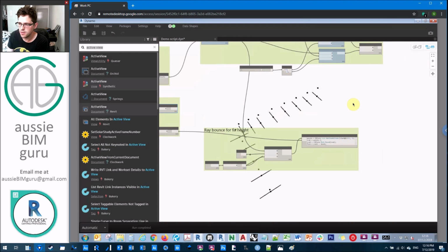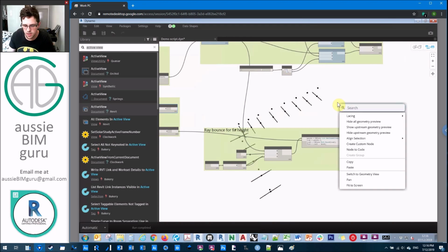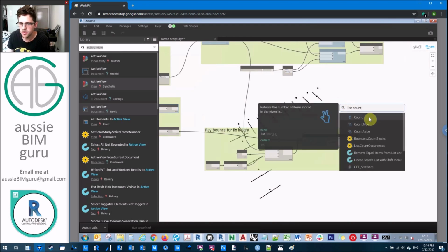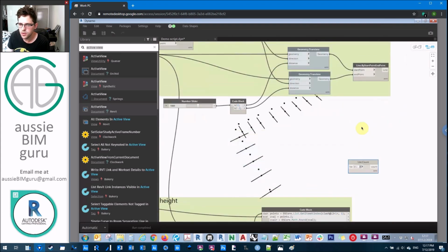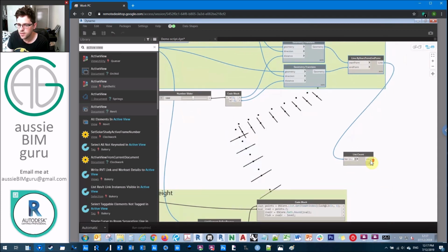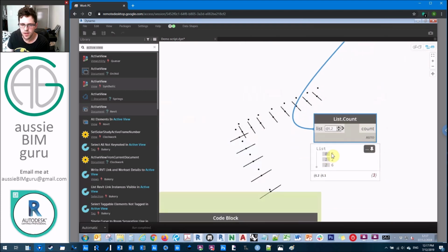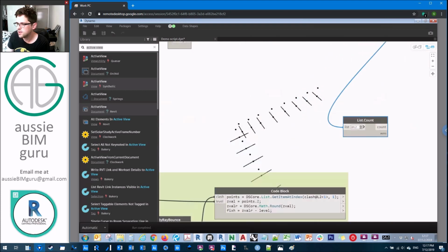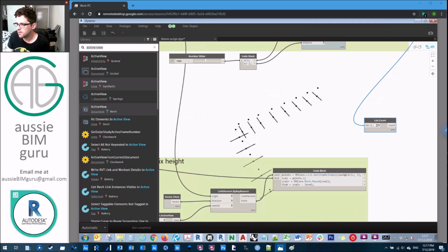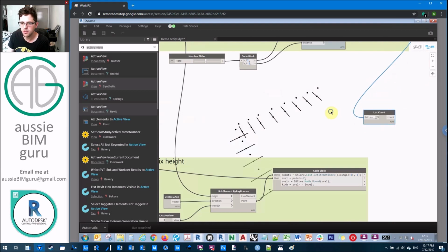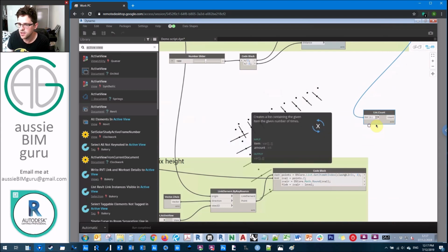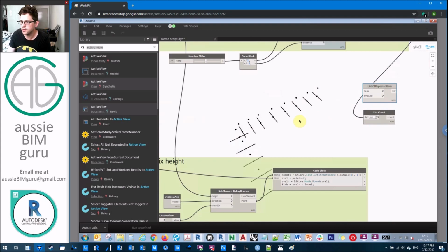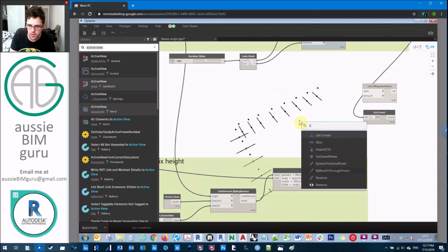So there's a few ways to do it. The way I'm going to do it is quite abstract, I guess. But what I'm going to do is count the number of supports on each duct. So from level 2, we're going to go and count the number of lines that we're dealing with so that we get 3 counts. We have 5 supports, 2 supports, and 6 respectively. And what I'm just going to do is feed this into a list of repeated item function. But I'm going to feed it over a list combine function, and I'll show you why in a sec. So we'll get list combine.